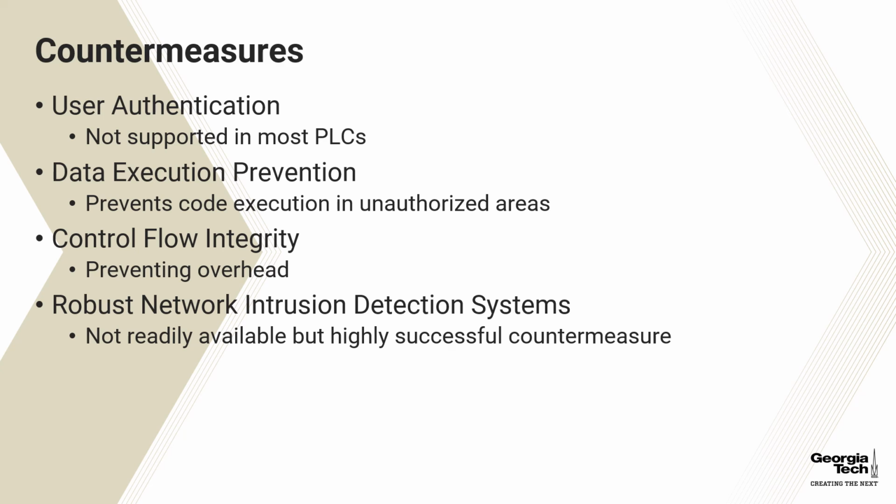Continuing right along, we have control flow integrity, or CFI. This seems like a great solution as it actively monitors the control flow and detects any type of change of plans. The real drawback is the overhead that would come along with such a solution. If a general purpose CFI solution is integrated, a customized PLC solution would need to be designed to avoid a hindrance in performance of real-time monitoring.